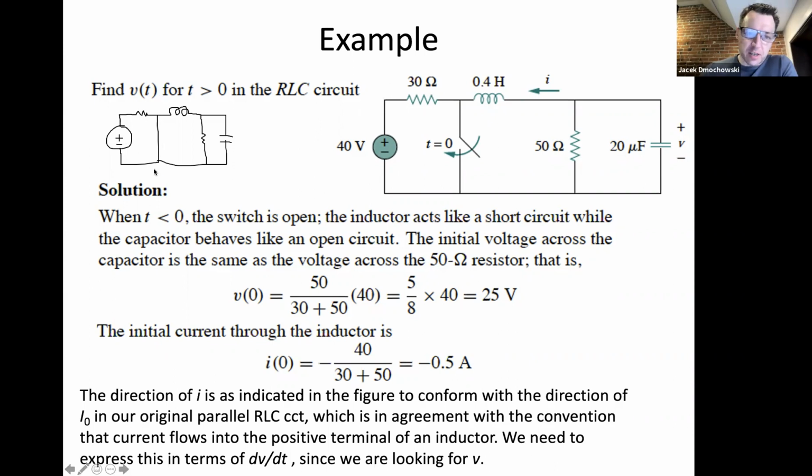Whenever you encounter a situation like this, you can basically separate this into two circuits, where one circuit is just the battery and the resistor, and the other circuit is the RLC. You can for all intents and purposes make them completely separate.